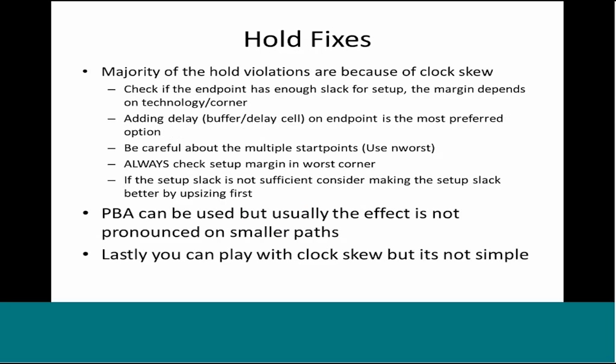Now, hold timing in some cases can be very easy, and in some cases it can be very tricky. The majority of hold violations are because of clock skew. This is why in synthesis you do not worry about hold timing. Let's say you are considering a single clock domain. You don't have multiple clocks. Pre-layout, you will not see any hold violations. Probably you will see very few hold violations, maybe on memory pins, not even on registers.